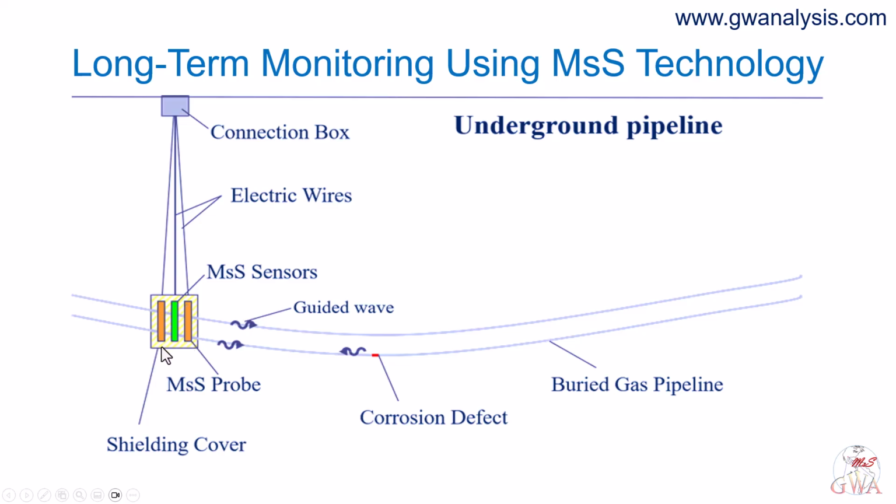That is all that stays permanently. The strip is thin enough to live under insulation or under coating, and the epoxy bond holds the coupling for years. Electric wires connect the probe to a connection box installed at an accessible location, and the coil is not bonded to the pipe at all.